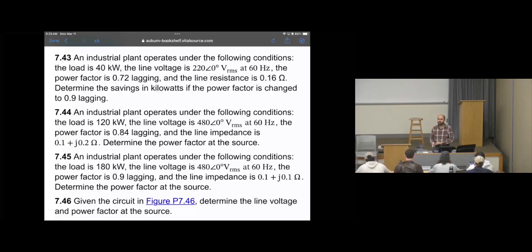How can I recognize whether this value is real power, reactive power, apparent power, or complex power? Look at this: it's only a value or a number, so definitely it's not complex power. Now I have three scenarios: is it real, reactive, or apparent? Look at the units. The unit is watts. Watts means real power, right?